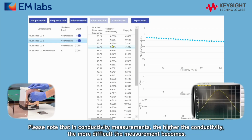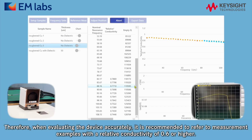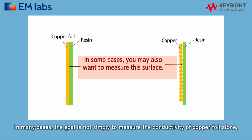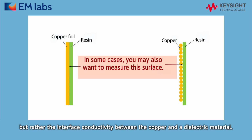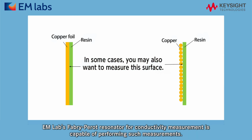Please note that in conductivity measurements, the higher the conductivity, the more difficult the measurement becomes. Therefore, when evaluating the device accurately, it is recommended to refer to measurement examples with a relative conductivity of 0.6 or higher. In many cases, the goal is not simply to measure the conductivity of copper foil alone, but rather the interface conductivity between the copper and a dielectric material. When copper is deposited onto resin by sputtering or evaporation, measuring the interface conductivity with the dielectric becomes essential. EMlabs Fabry-Perot Resonator for conductivity measurement is capable of performing such measurements.